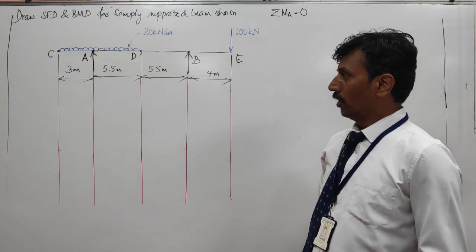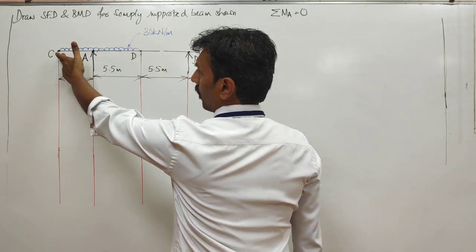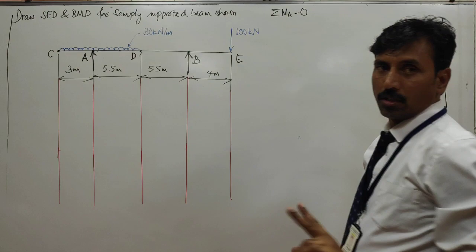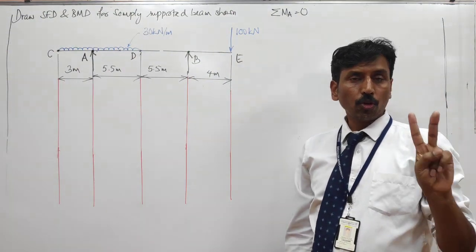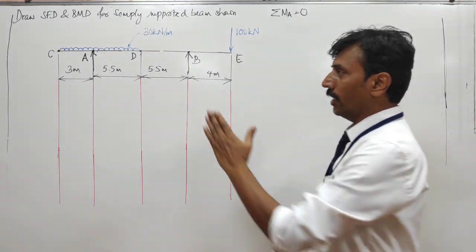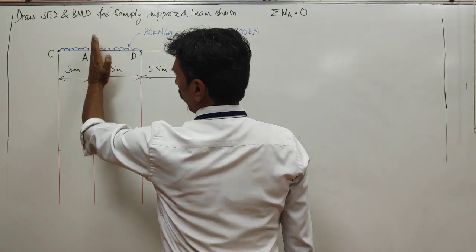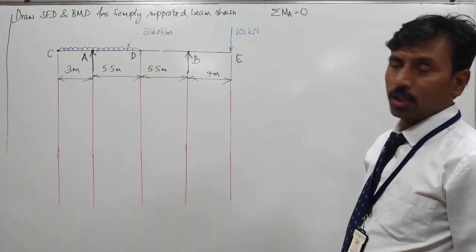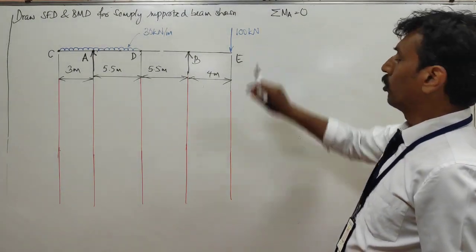Therefore, if you take at C, then you will have the reaction force at A, reaction force at B, both in the equations. There will be two unknowns. If you got two unknowns in the equation, you can't solve. So therefore, you should take at a point where one of these is unknown. Only then you can get the other unknown. Okay, so I am taking about A.